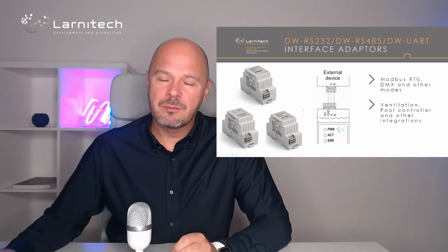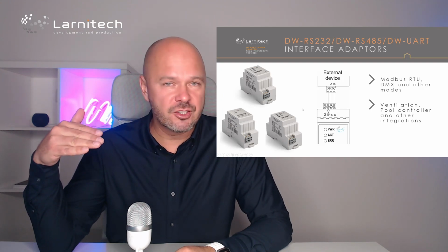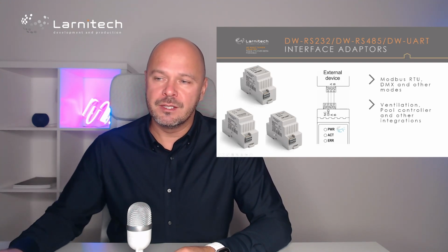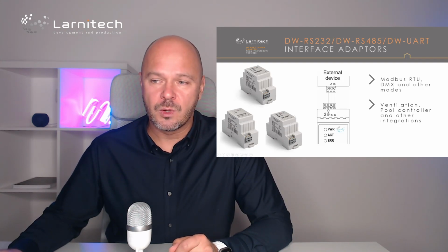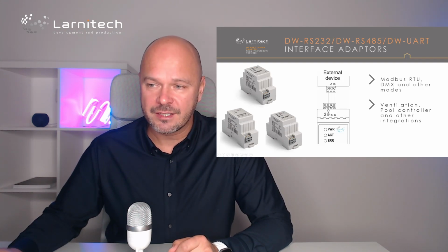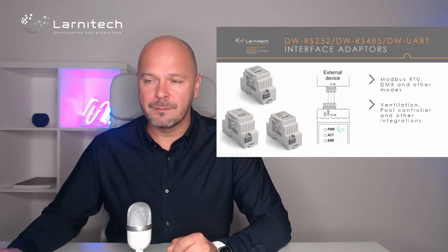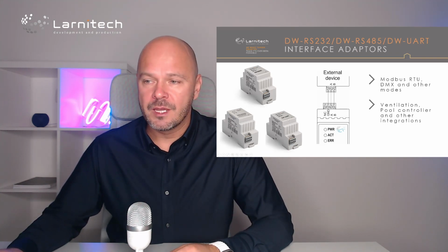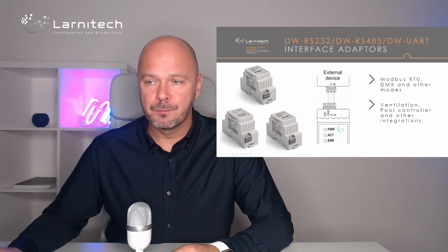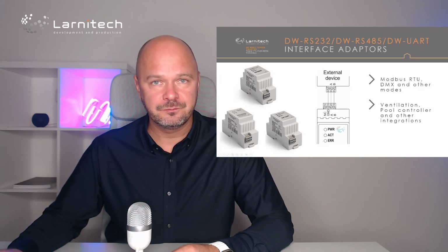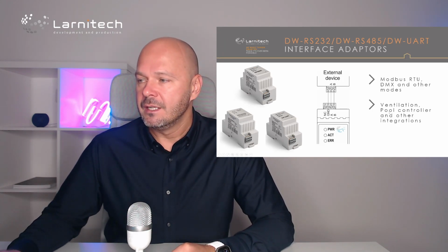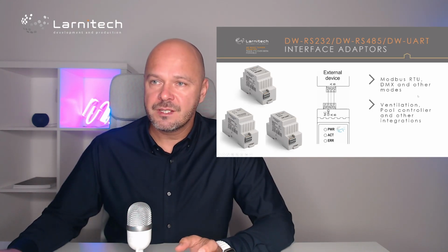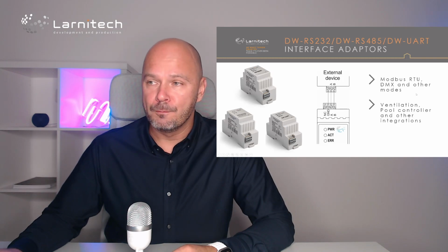UART is a more low-level connection to the device, and sometimes you need it if you want to connect to third party. So it's not widely used, but sometimes you can connect to some air conditioners, or maybe some controllers which do not have other connection, just UART. So this is what these guys are for.